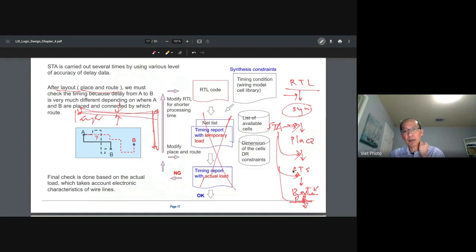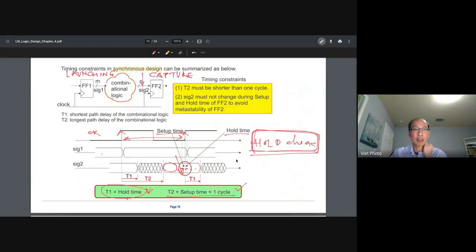The next step after that is to route the design and do post-route optimization. After this you have the complete design, where all the data paths are routed and everything is complete. At that time, the timing is correct.